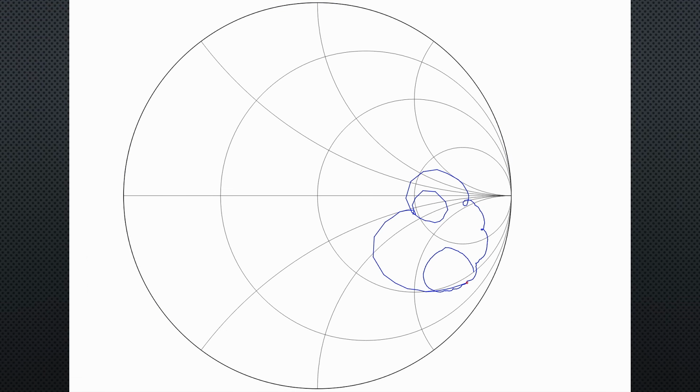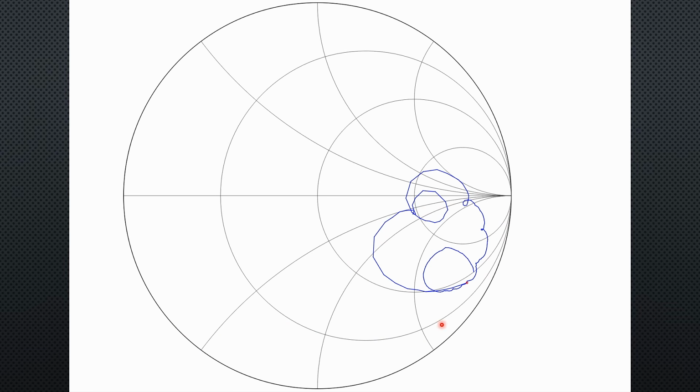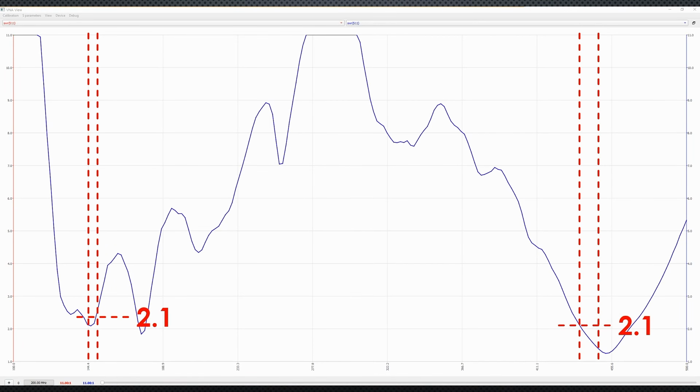If we look at the Smith chart, we see that its curve always is in the capacitive area. Maybe adding some inductivity would get a better response. The real one is far from an optimal antenna, but its dips at least are in the right place. We could now calibrate our VNA around 144 or around 430 MHz to get better measurements for the 2 ranges. But I think you got the point.